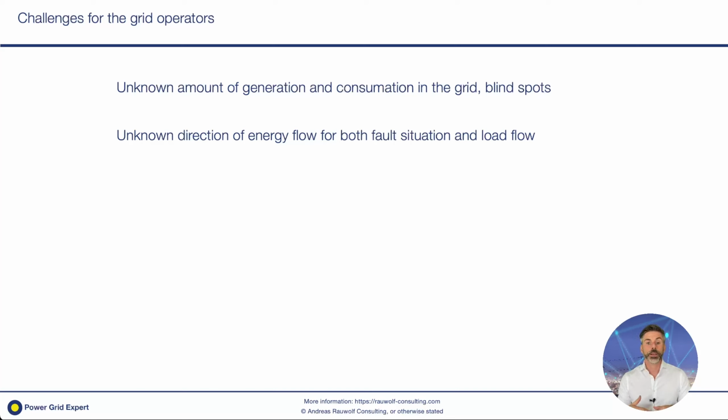It might be that the transformer, which is basically thought to supply the customers, is actually feeding back to the network, because the energy is not needed locally, so it's fed back to the next higher voltage level. And if the cable is not big enough, if the consumption is not high enough, we can have problems in voltage levels. If we're feeding too much in, the voltage goes up, of course, and that is only possible and allowed for a very narrow range.